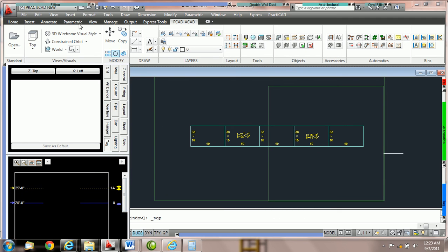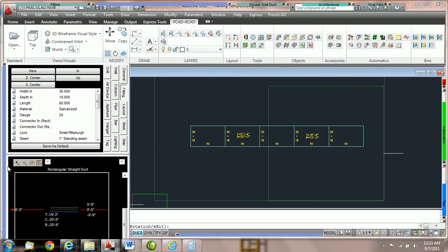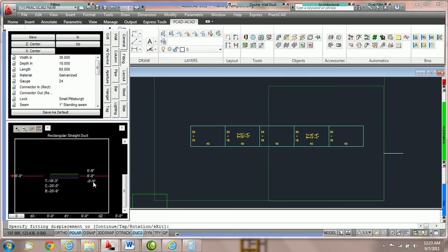Once again, we can toggle between relative bottoms and we can tag to different reference points. If we're going to come in here and grab a second duct line, this time we're going to say, let's tag this duct 5 foot above this slab. Well, what I can do is I can come into my elevation box, fit to view, and say, I want my relative bottom points that PractiCAD's reading to me. I want PractiCAD to read it to me from 1A mark. So I click on the blue right here. Turn that blue. PractiCAD has switched it.